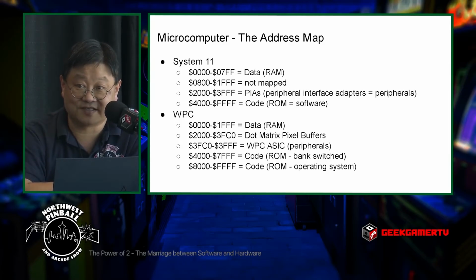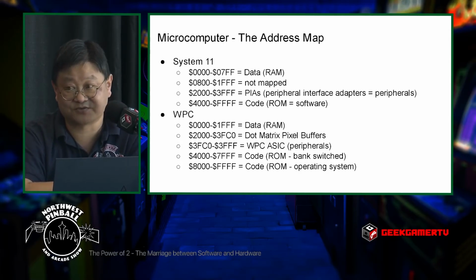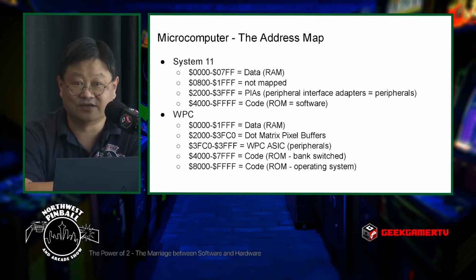So what this does is it allows different groups of 16K of code to be swapped in. You can put different functionality in different banks, and you have to switch that bank enabled in order to touch that code. And there's special code in the 8000 range that does the bank switching. Since it's always mapped, it's always the same code. If you try and bank switch 4000 to 8000, you'll swap in some code that is not yours while it's trying to execute it, and bad things will happen.